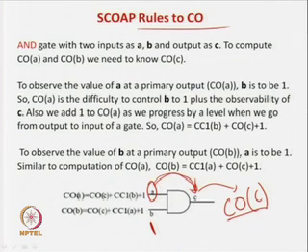So, to observe this A, what do we need to do? First we need to make B 1, so the combinational controllability of B to 1 has to be accounted for. Then, if you apply a 1, A will be reflected at C, correct. But how difficult is it to observe C? A is now reflected from here to here by applying a 1 over here. So, the difficulty of combinational observability of A is that you have to make B as 1. But by making B 1, A is only propagated to C, it is not yet propagated to the primary output. So, how difficult is it to move it to a primary output?